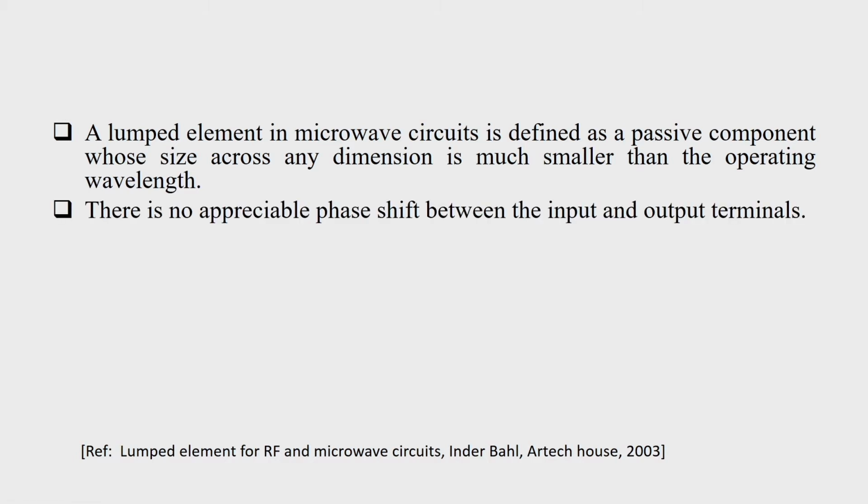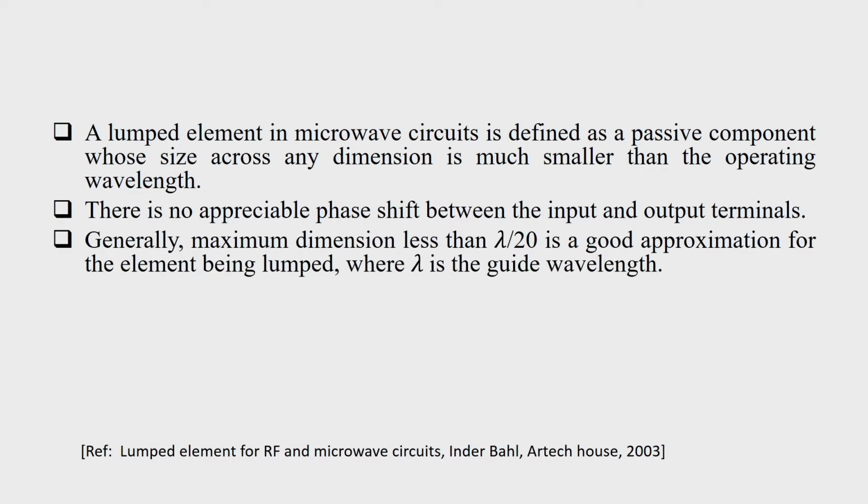There is no appreciable phase shift between the input and output terminals of this type of lumped element because of their small size, and generally maximum dimension less than lambda by 20 is considered as a good approximation for the element being lumped, where lambda is the guide wavelength.